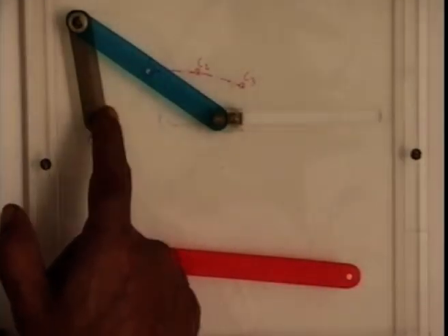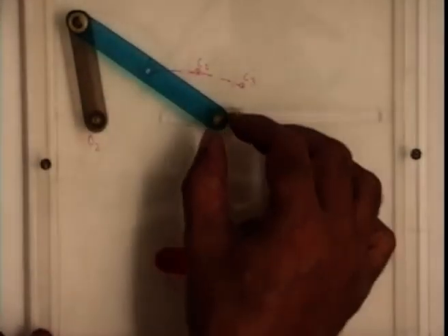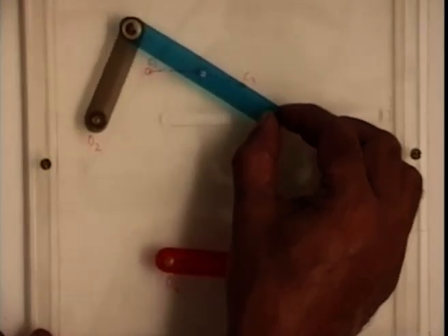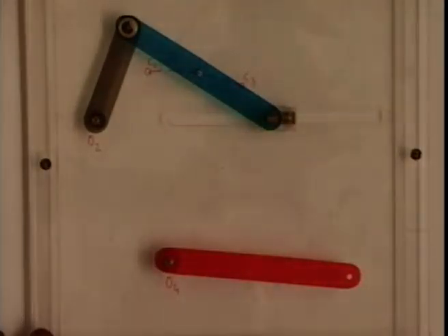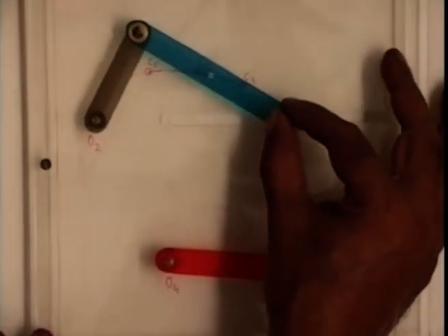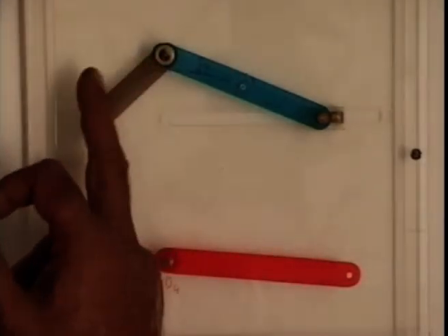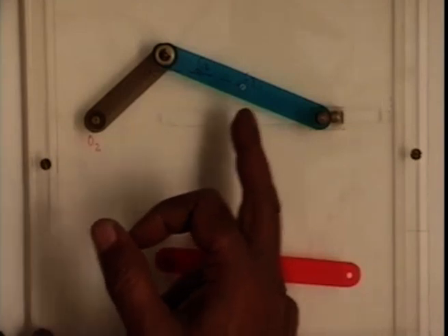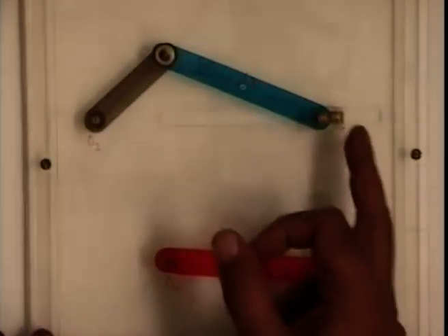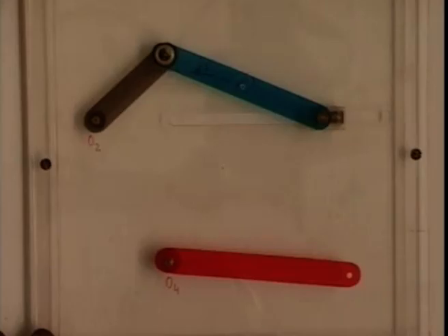This is the slider crank mechanism such that this pair of coordinated movement from first to second configuration and second to third configuration can be designed. This we have done just now. If we specify theta 212, theta 223 and the corresponding S12, S23, I can always design this slider crank mechanism.